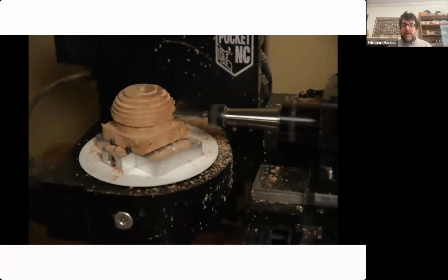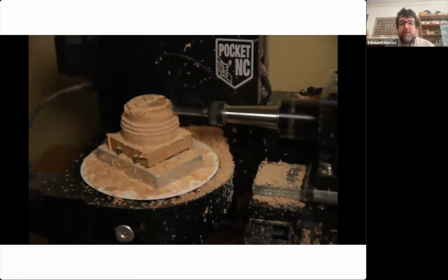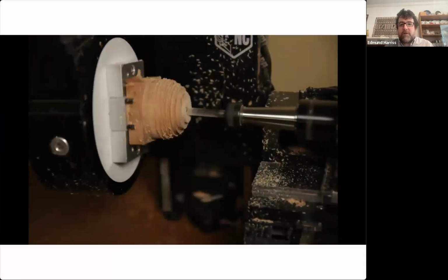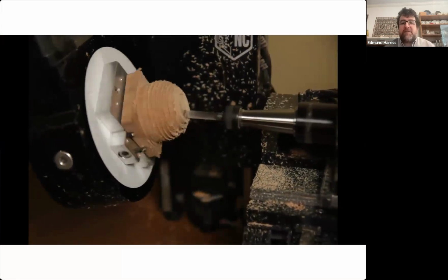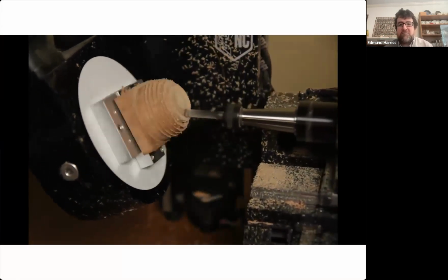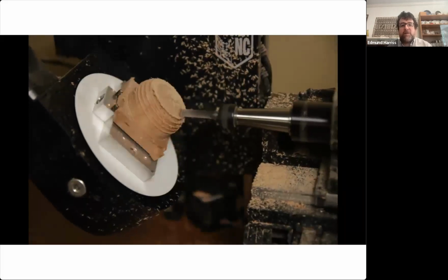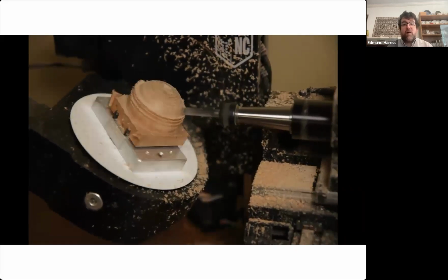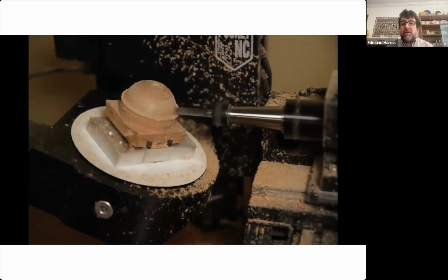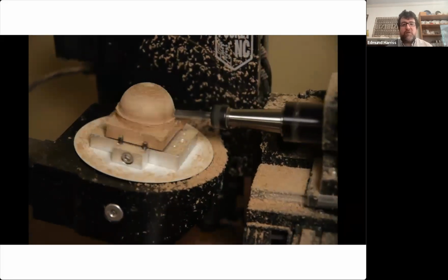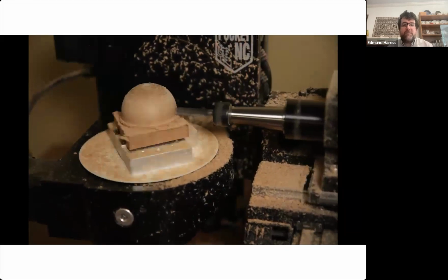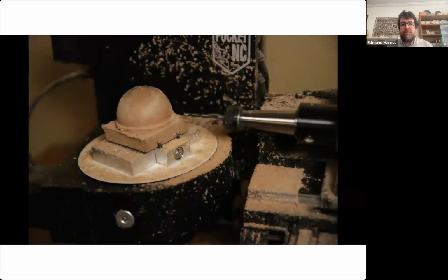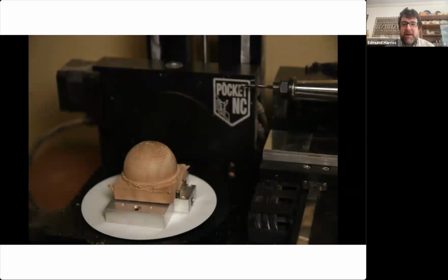And so here is an example of the machine running. So by changing the direction, we did some roughing where we just did the rotary, and now we're rotating, and the tool is staying always at right angles, always normal to the surface. And so we're able to not just produce curves, but we can actually mill out the surface of a sphere here. And then you can have some fun cutting into the sphere